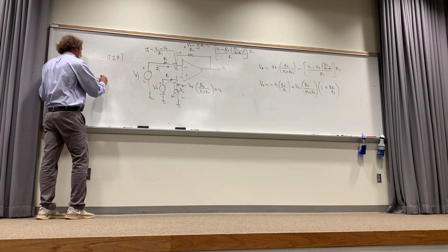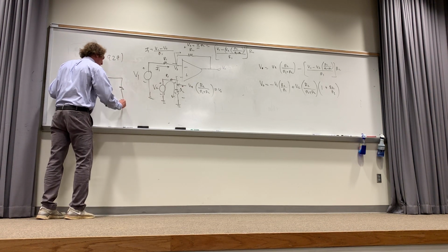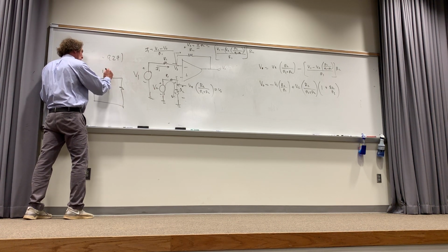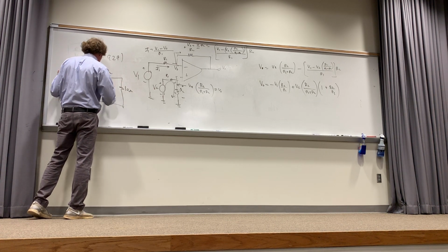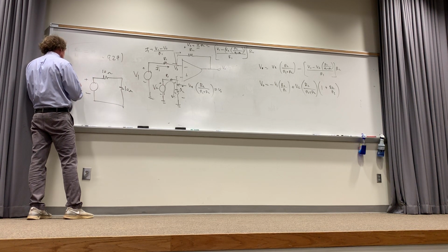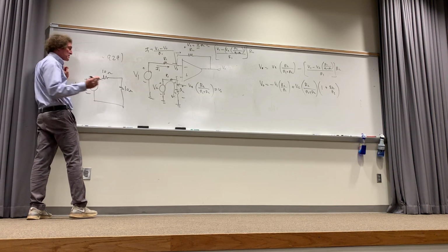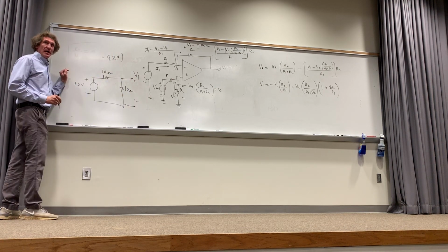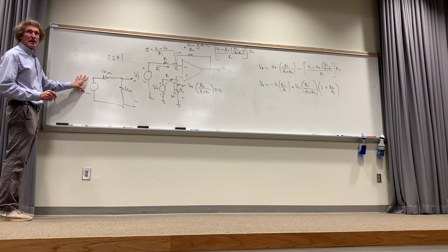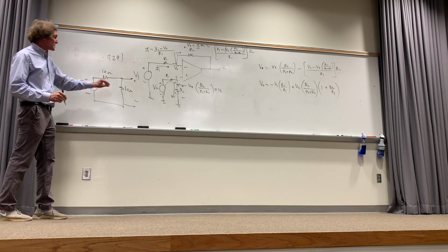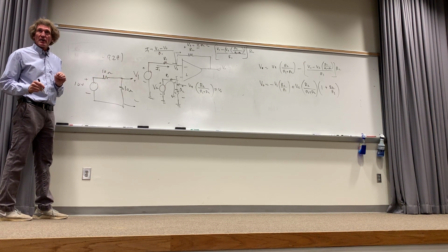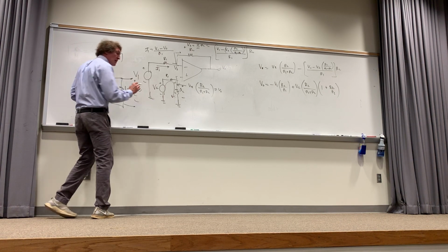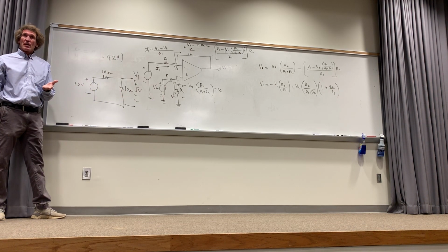Look, I'm not sure if maybe the drawing is causing a problem or what. If I have this circuit, make this 10 ohms, make this 10 ohms, and make this 10 volts, all right? Simple as possible. And I want the voltage between here and here. That would be 10 times 10 over 20, right? Or it would be 5 volts. Do you agree with that? Agreed? All right, 5 volts.